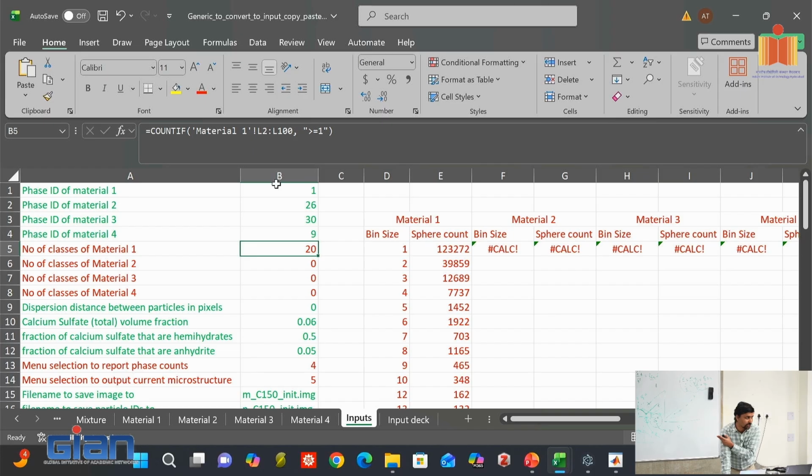This one has 20 different sizes that are required to be kept there. The green part that you see is the dispersion factor, which is basically how close you want your particles to be. Is there something repulsing your particle? Do you want to make sure that they are apart? Then you can play around with this. I think this goes from 0 to 1. Depending on the numbers, the particles will be placed closer or farther away.